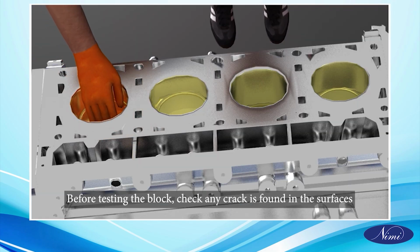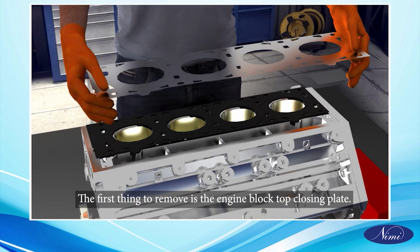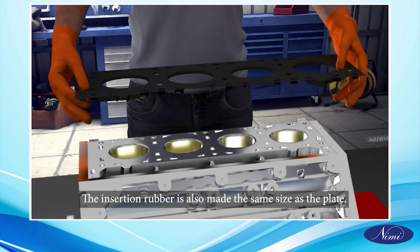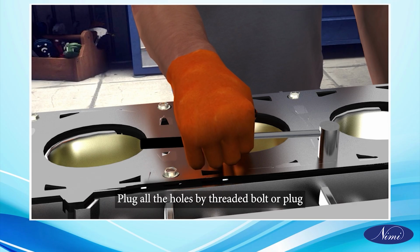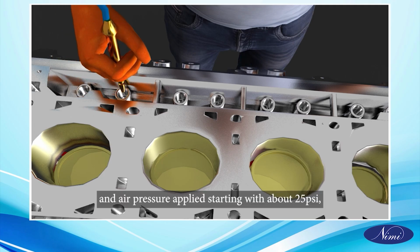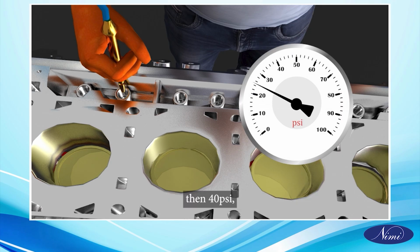Before testing the block, check if any crack is found on the surfaces. The first thing to remove is the engine block top closing plate. The measurements are taken from the engine block itself. The insertion rubber is also made the same size as the plate. Plug all the holes with threaded bolts or plugs. The first test was carried out with just air pressure, with the block inverted and air pressure applied starting with about 25 psi, then 40 psi, then 60 psi.